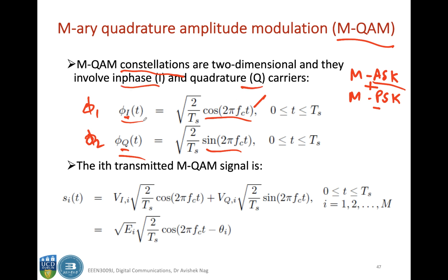You remember we also applied this concept when we were doing QPSK. So we have this in phase and quadrature components. Here also we have these two axes, which are the two basis functions given by this cosine and sinusoidal waveforms, and we can define them as in phase and quadrature components.